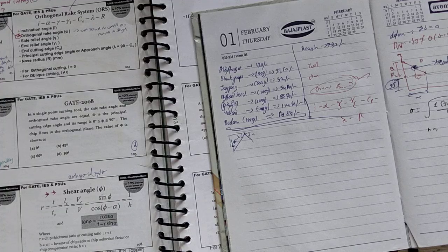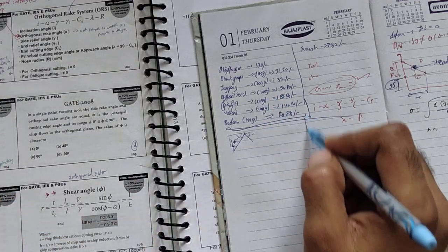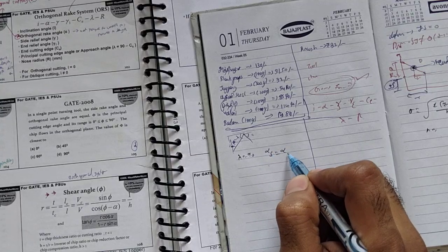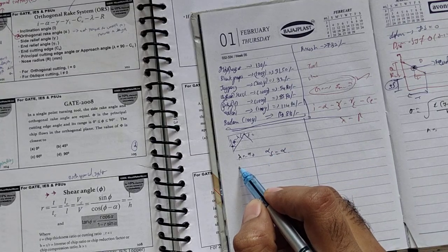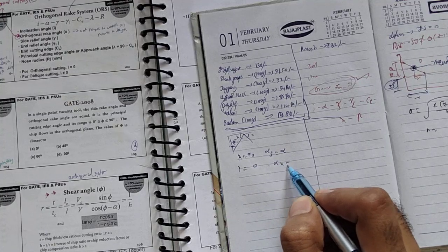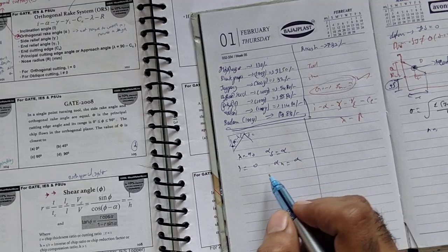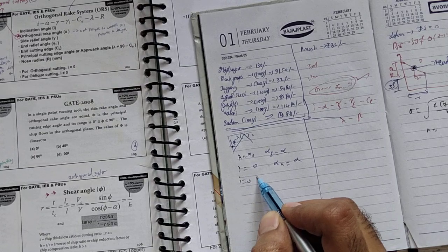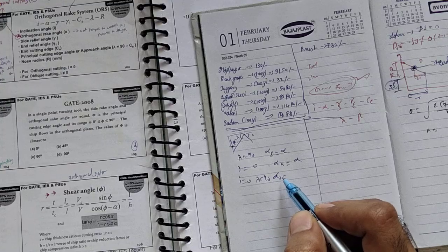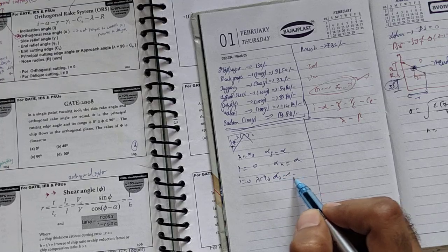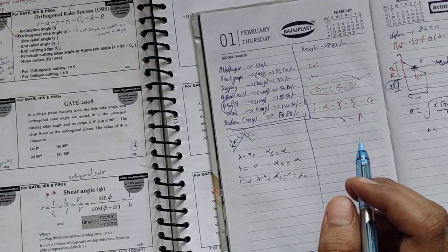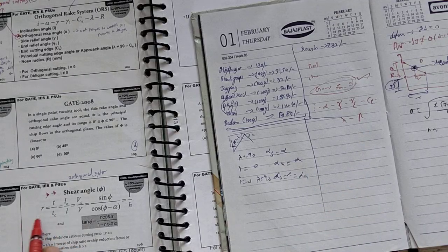How to, okay? Suppose lambda equals 90 degrees, so the side rake angle is equal to the orthogonal rake angle. If the inclination angle is equal to 0, it means the normal rake angle equals the orthogonal rake angle. Suppose if i equals 0 and lambda equals 90 degrees, then the side rake angle, orthogonal rake angle, back rake angle, and normal rake angle are all similar, okay? Next, I think you don't know about this one.